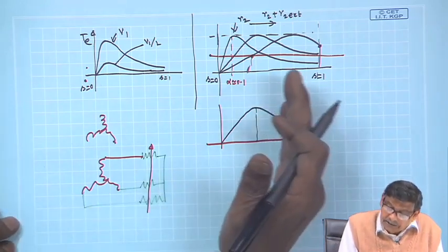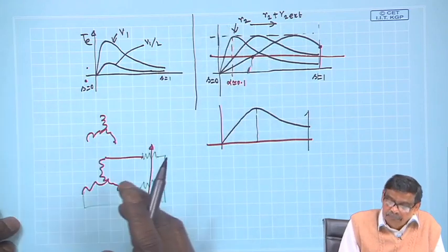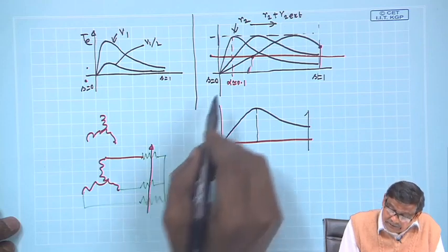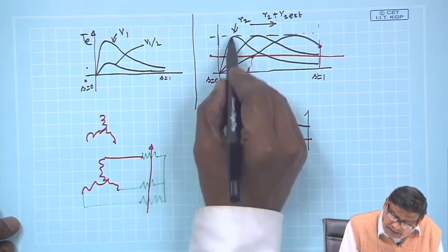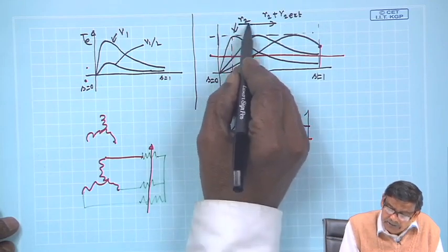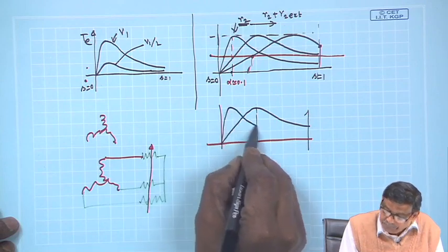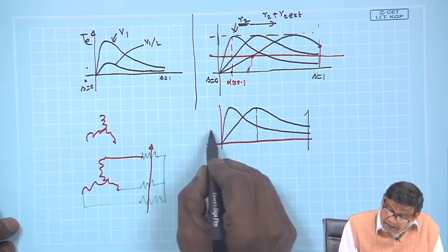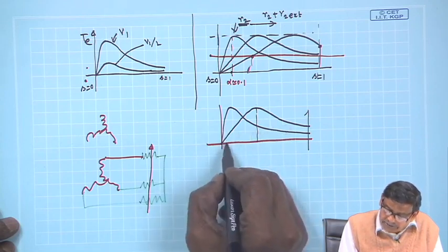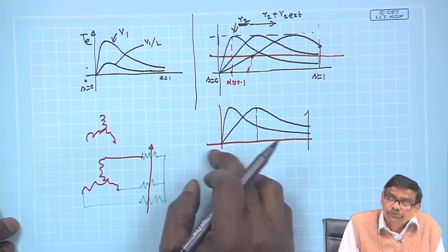Therefore, people try to see that R2 when it is operating should be low, so that rotor copper loss is reduced to a great extent, and that is why you select this value of alpha, which depends upon inherent rotor resistance. It should be like this, and at full load torque, whatever it is, the point of intersection will decide the speed, which I know will be close to synchronous speed.